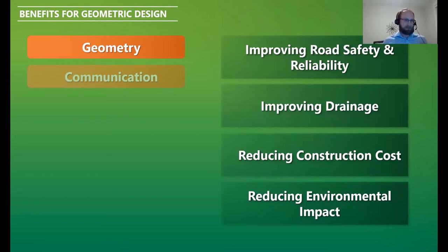So you can set your cross section to be an appropriate width. You can have your appropriate surfacing layers on it. You can plan where your ditches are. You can plan your cut slope angles, fill slope angles. And then the really nice thing is that you can move your center line around, and it's going to update in real time to show you that, oh, if I move my alignment over here, my fill slope's spilling out into an area I don't want to affect that creek. Or maybe you have a long fill slope and you should be pushing into a full bench section. Maybe you click around and you realize, oh, I can miss that full bench section. So there's just a lot of the benefits of how interactive it is.